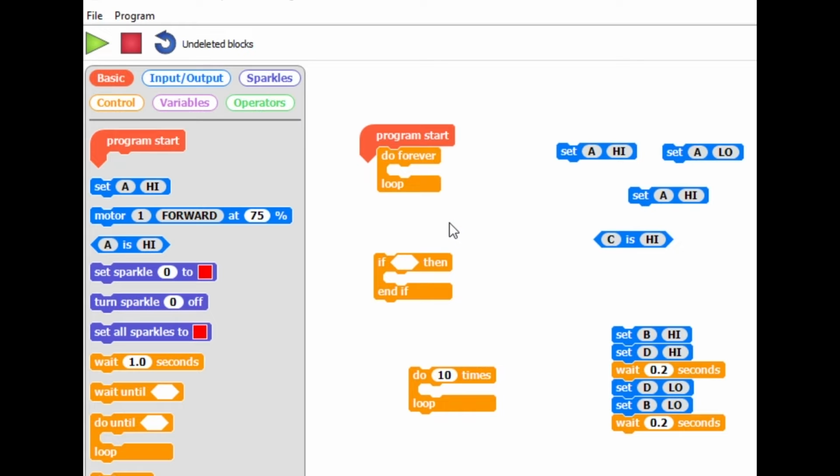And the first thing we want to do is to make sure the traffic light, or the Pelican light, is on red as the default state. So it only changes from red if there is a button press on the button. Remember that the traffic light red is the A port, so we're going to set the red light as high, and that will be constantly on unless something else happens.